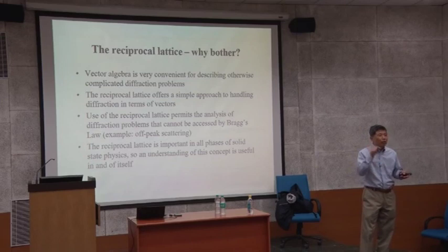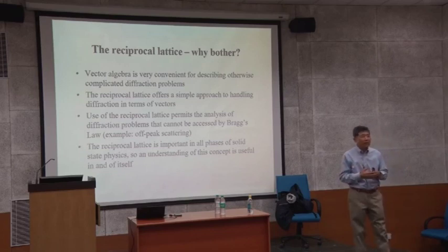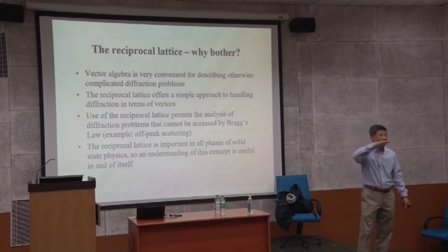Then beyond this, you're drawing more and more unit cells, so messy that you don't know what it is. Is that true? So you really cannot describe it. It's because X-ray diffraction basically comes from arbitrary planes. The HKL plane is a diffraction plane, but the plane does not exist. A plane is actually arbitrarily drawn on the real-space lattice. But you cannot draw many planes in the unit cell.